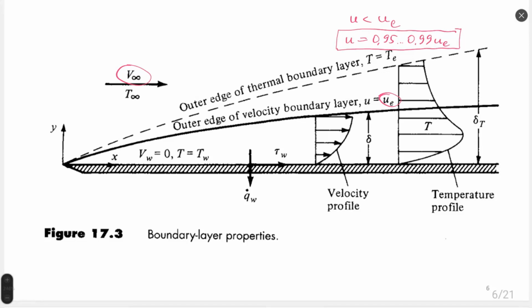And there is also a boundary layer associated with change of temperature. Due to heat transfer process, temperature profile also happens. As you can see on figure 3, there is a typical temperature profile where on the wall the flow is cooler near the wall, right?